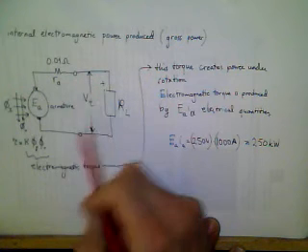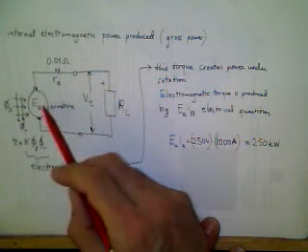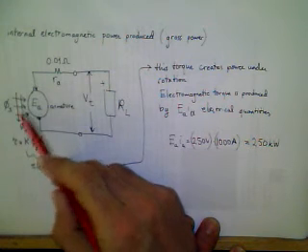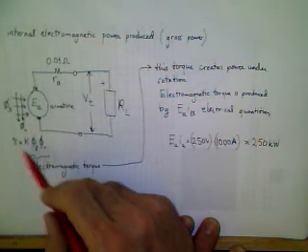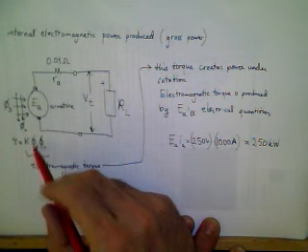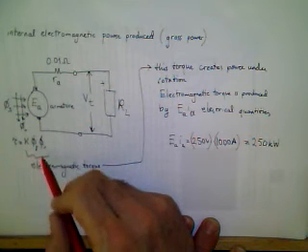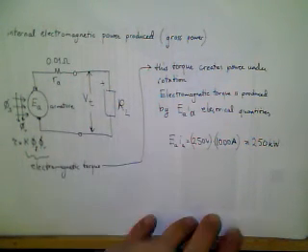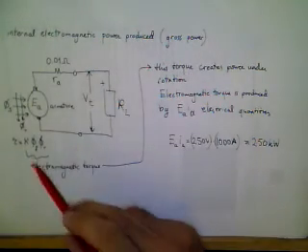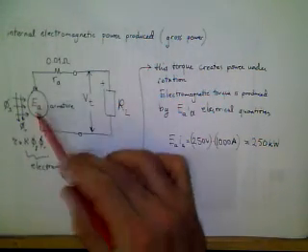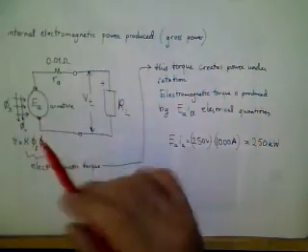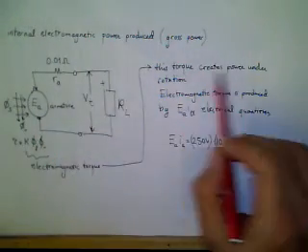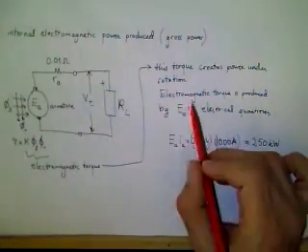Part B, internal electromagnetic power produced by this machine. For the armature side, we have calculated the armature voltage. Under the field excitation, the torque is proportional to the field flux and associated rotor flux, multiplied by a constant depending on the number of windings, geometrical structure, size, length, etc. This torque creates power under rotation.